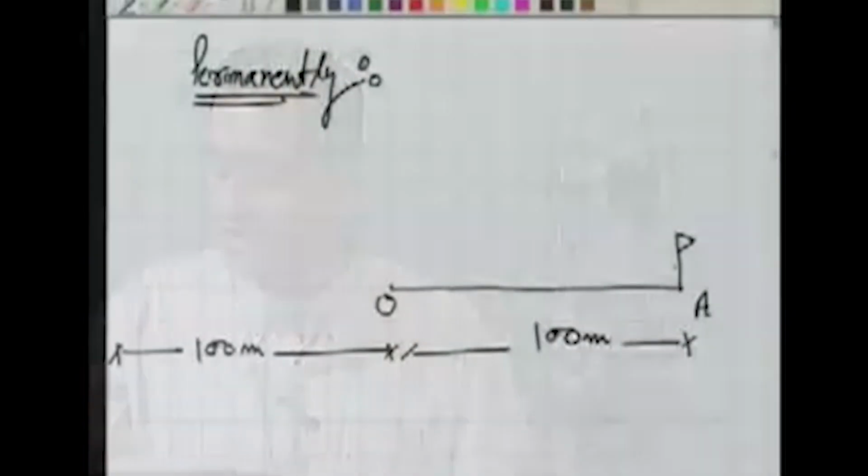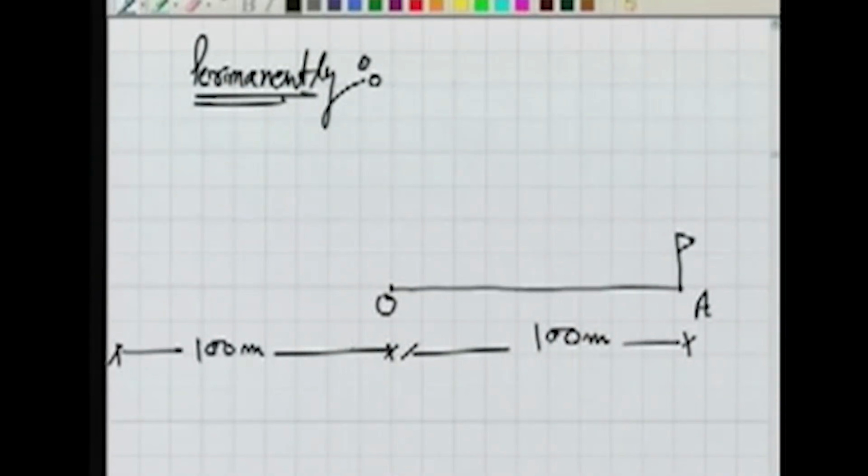All these leveling and other things are done with the instrument. I now bisect that ranging rod. So this ranging rod here is bisected while the instrument is here. Let us say we start from the ideal case. There is no error in the instrument because of shifting of the cross wire. The cross wire is here only, in the center. If it is in the center, it will form a vertical plane. While I am rotating the line of sight, it will mark a vertical plane.